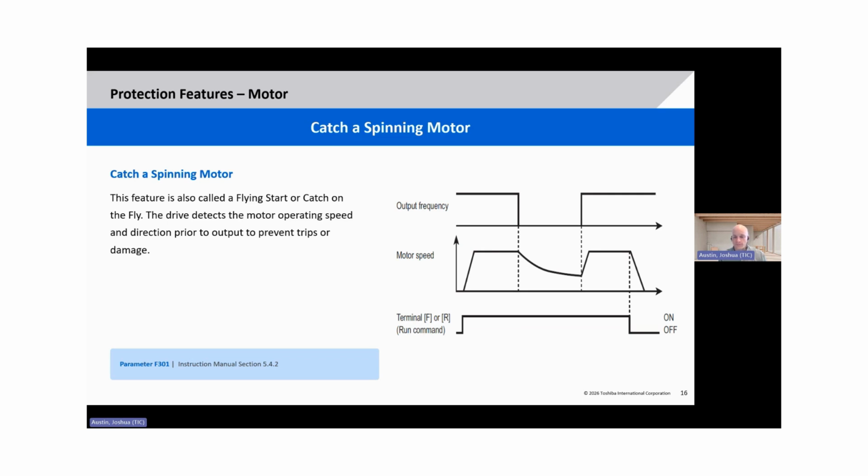VFD starting the motor. And so what we can do, prior to outputting a frequency to the motor, is detect the direction and the speed of operation of that motor and match it with the output frequency. And what this does is prevent stress and overheating and overcurrent conditions on the motor.